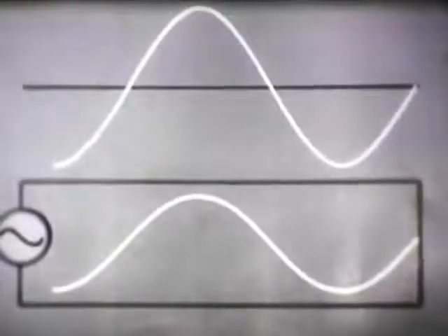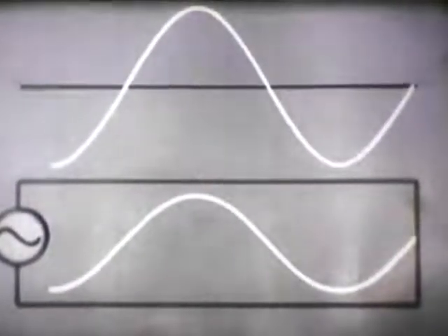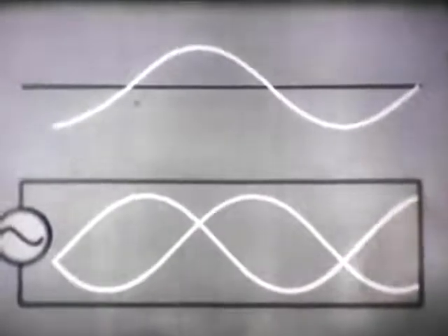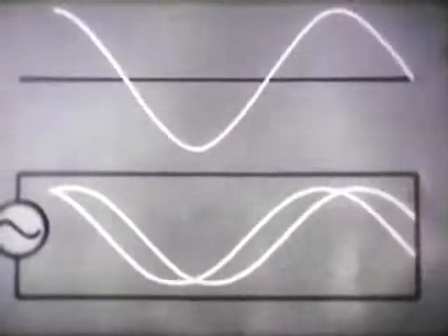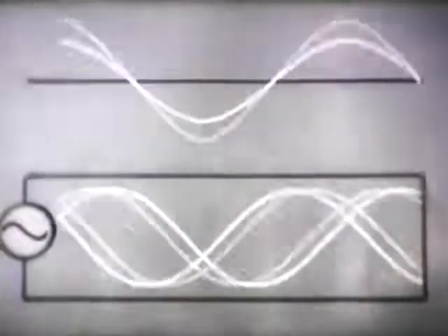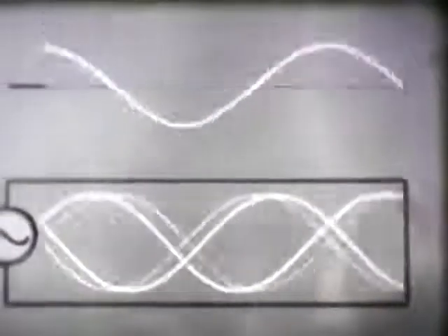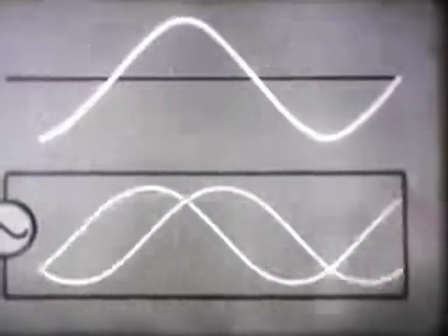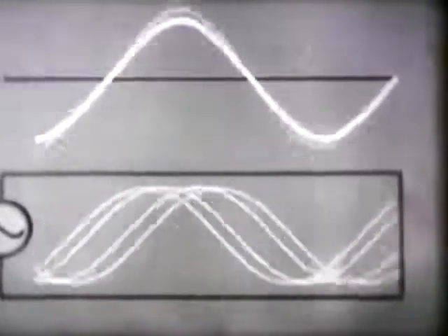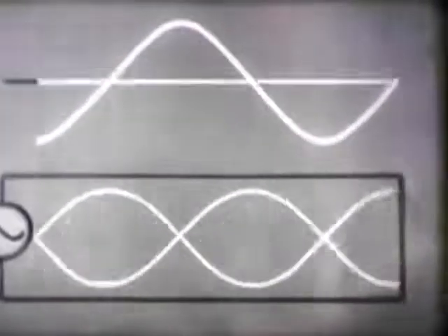With three readings, we've gotten three sets of values for one standing wave. A measuring of all possible values of the standing wave will give us a picture of the varying values that exist between the constant zero points. The reading of the standing wave you will get with a current or voltage indicator is the effective value of these many curves. This value, of course, remains constant.